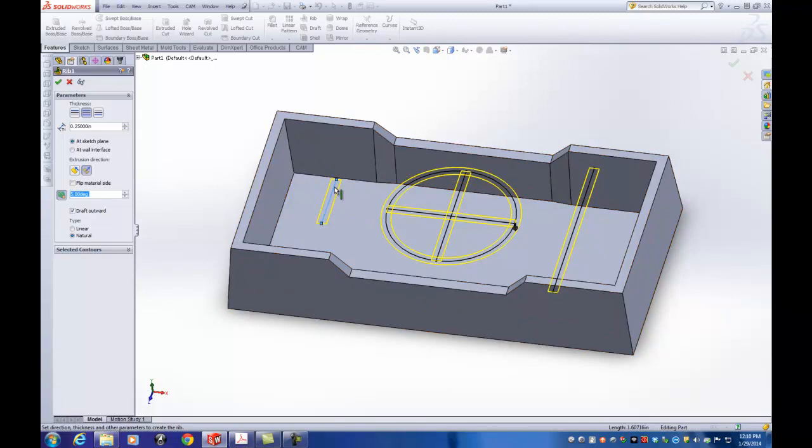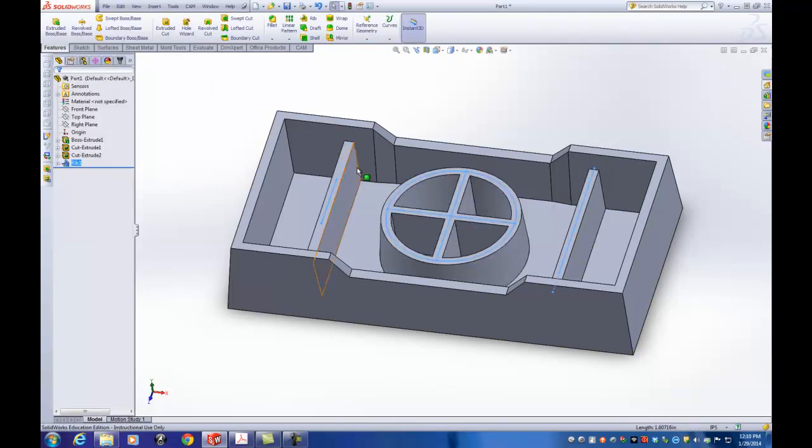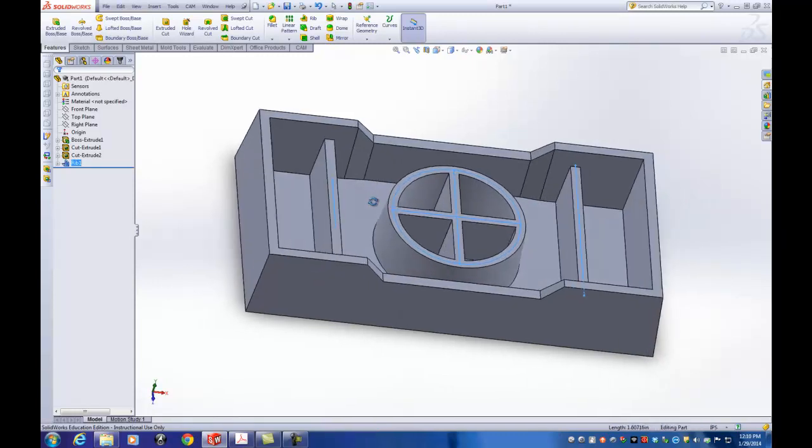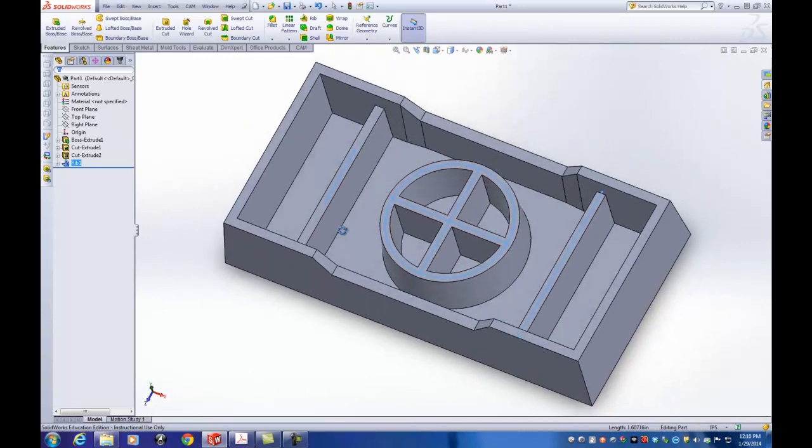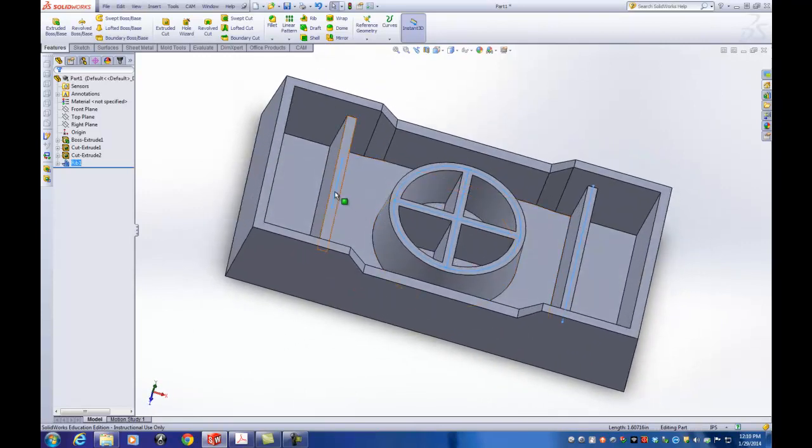When these ribs are created, it's just going to extrude out from those edges to the nearest faces. So even this one that's not touching that face will still fill in. So when I hit the green check mark, it filled in all the way across and all the way down because it's just coming from that line and extending out to the nearest face. That feature there of the rib extending out from that line to the nearest face was what you needed to see.